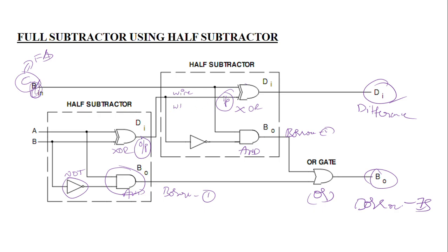If you want to connect an output port to another input port without any storing of values, then you simply declare it as a variable and make it a wire data type. Here we can observe there is a wire which connects the output port to the input port. It just carries the data of the output of the first XOR gate going to the input of the second XOR gate. That's why I simply declare it as a wire.